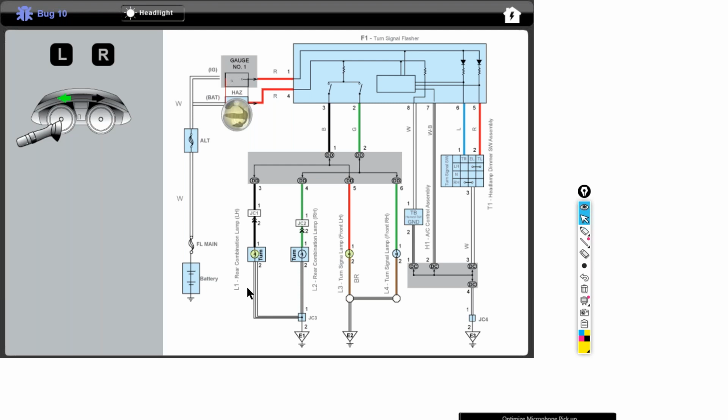Makes a very effective, simple diagnostic tool for shorts to ground, and you will not overheat wires, you will not damage the wiring. I've seen so many times guys start using stuff in there, keep putting larger and larger fuses. Well, they put a fuse in there, it can handle more current than the wiring and melt the wiring. So that's not a good thing at that point.